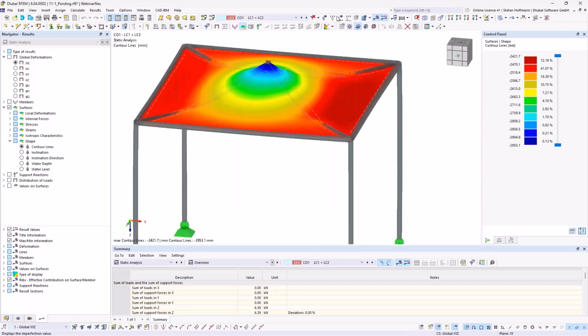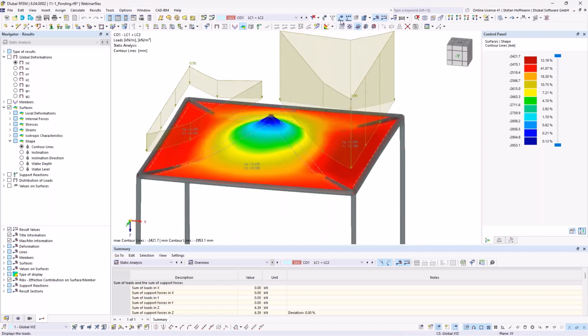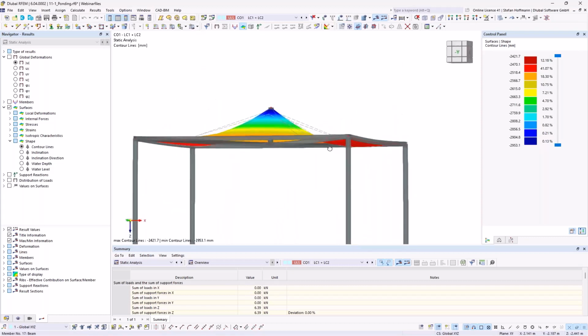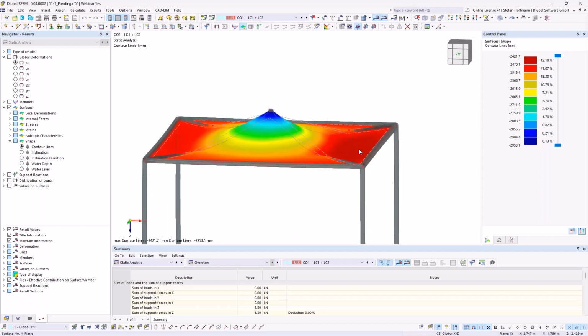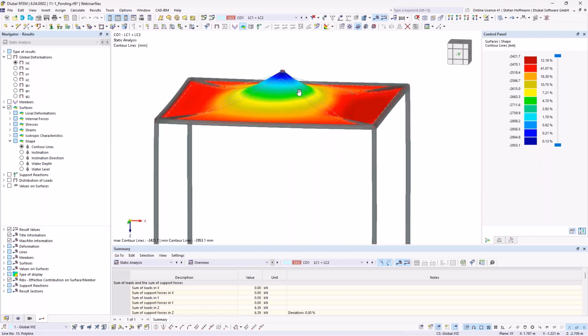And then there is the, let's call it heavy vertical load. And as you can see, my membrane will, due to the effect that the load is higher than my pre-stress, bend down. And the highest point of my members are 2.50 meters, and my membrane will be like 8 centimeters below this point. So this is most likely the lowest point, and this is an available point for water to accumulate.